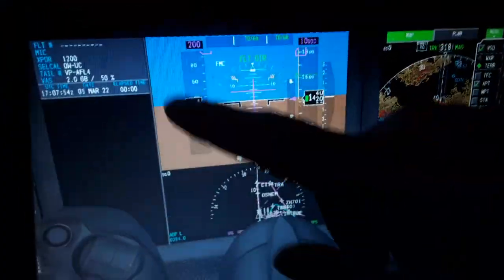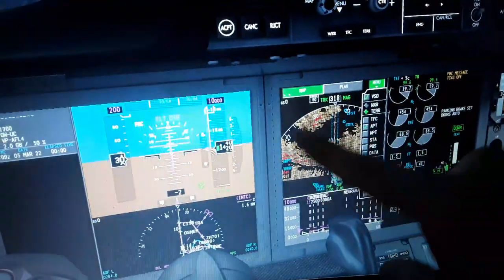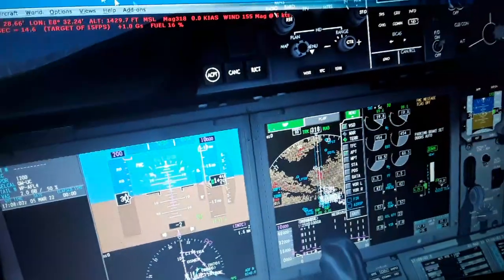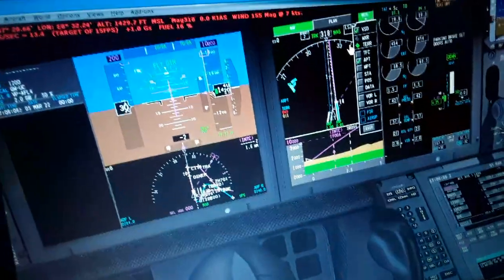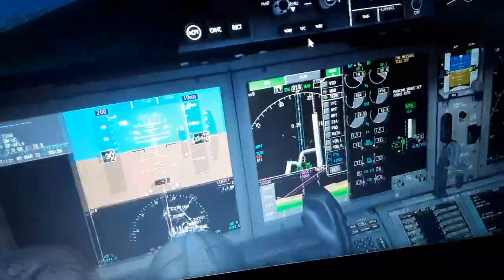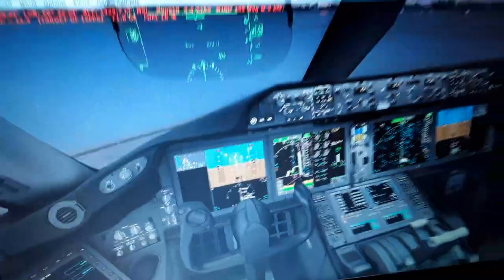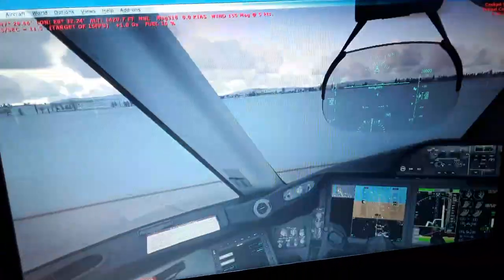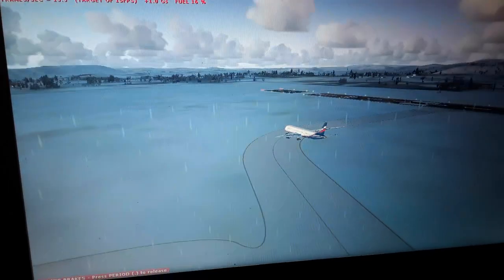In the primary flight display, we have the HSI again, the flight plan displayed. And in the navigation display, we have the horizontal and the vertical flight plan, the flight path as we're going to be flying, so you see both what happens horizontally and vertically over here. Also in the navigation display, you can see the runway where we are located right now. Over here is the taxiway, runway 14 and runway 16. If you look around here, you will see the GPS is correct. You can also see outside the runways and the taxiway is the same one as displayed in the GPS receiver.